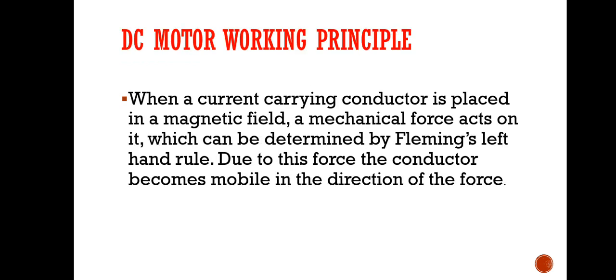DC motor working principle. When a current carrying conductor is placed in a magnetic field, a mechanical force acts on it, which can be determined by Fleming's left-hand rule. Due to this force, the conductor becomes mobile in the direction of the force.